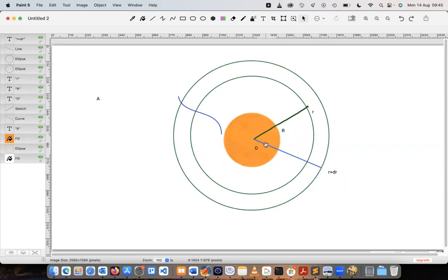When we define our variable, our direction, we always define where the zero is and in which direction it's increasing. So clearly the most logical choice for r would be the center is here and we are pushing out away from the particle. So whenever we write our material balances, we regard flux in at the lower value.